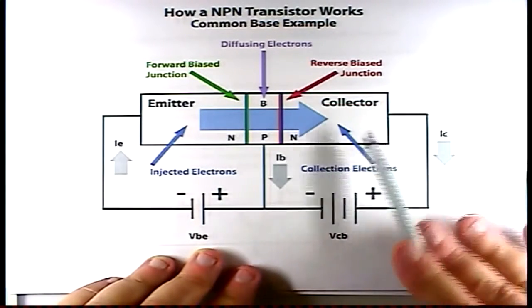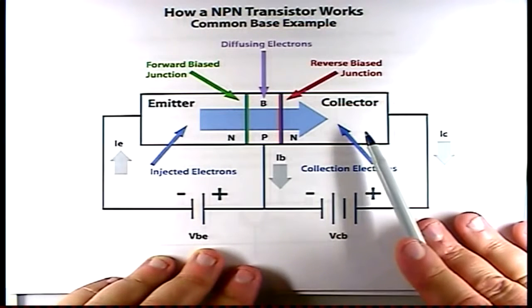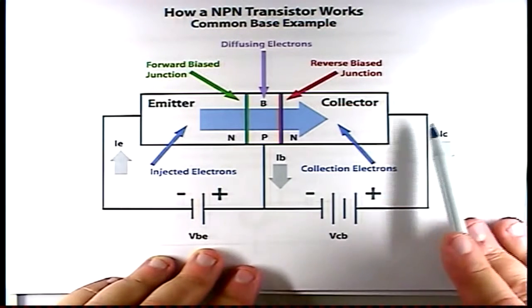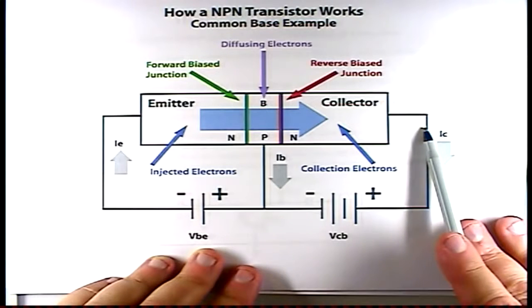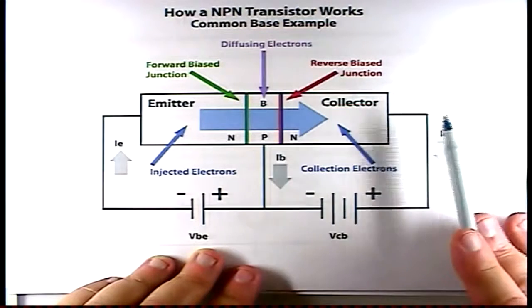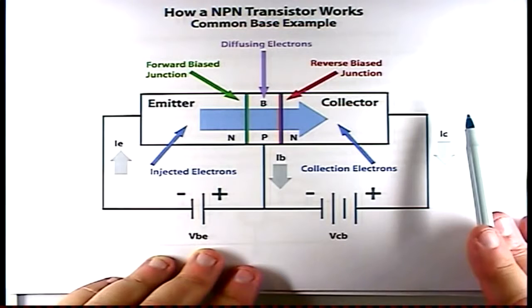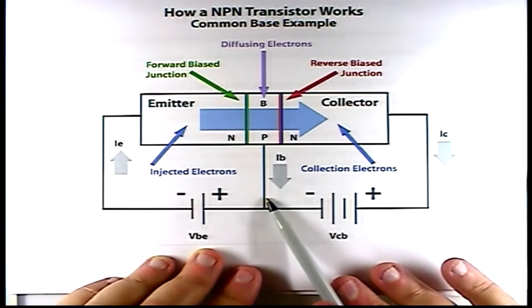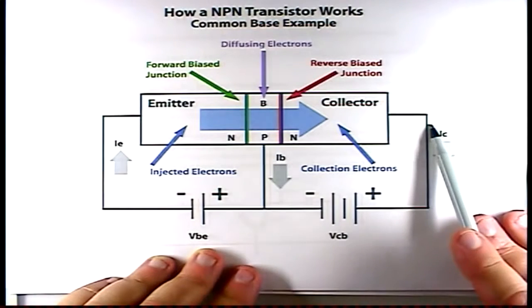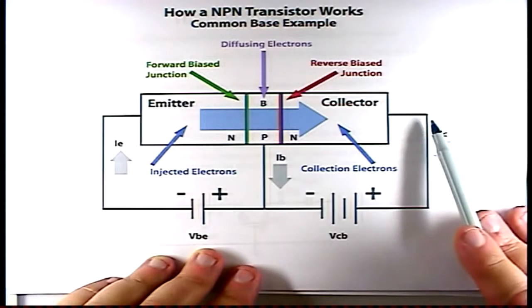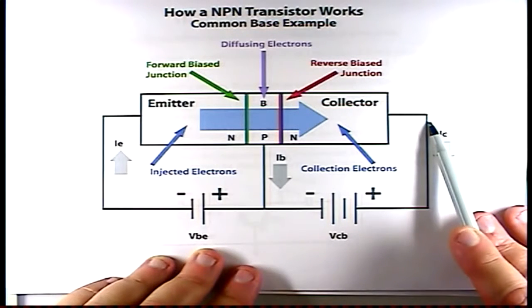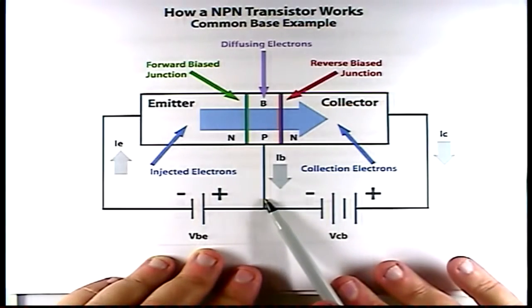And so we have a nice clean current flow change when we take this across a dropping resistor over here on this end. We drop a voltage across that resistor. We're going to see a nice clean voltage change when we have a voltage change on the input to the base, except this voltage change is small and this voltage change is large, but the voltage change on this output here is proportional to the voltage change that's applied to the base.